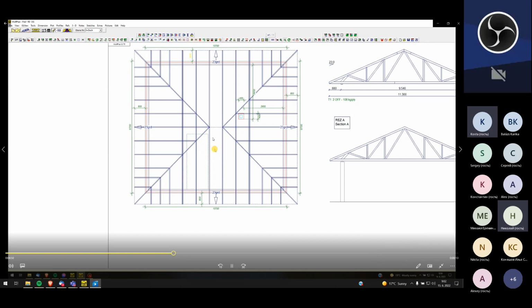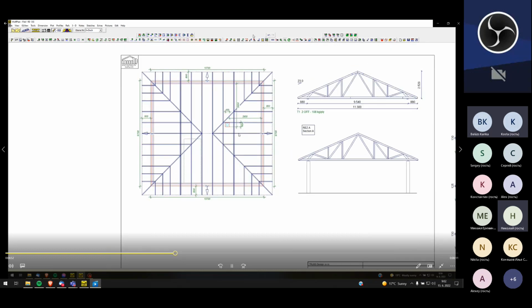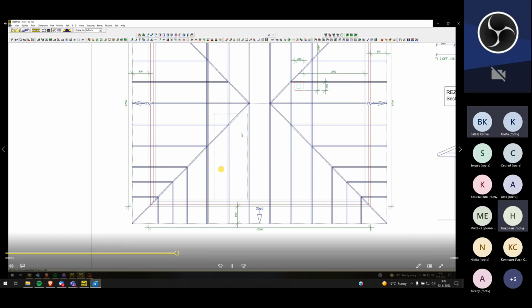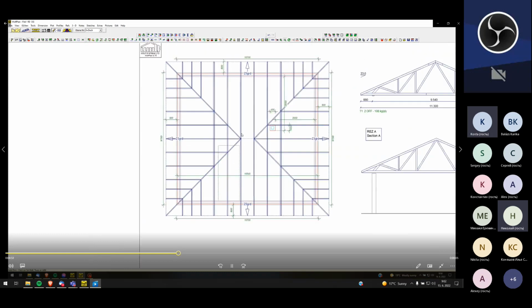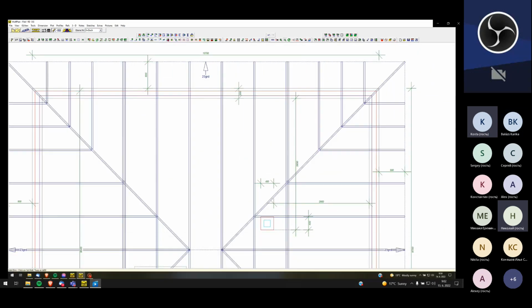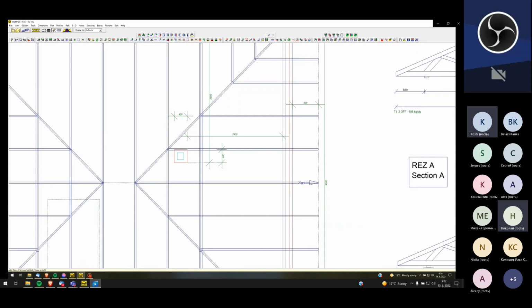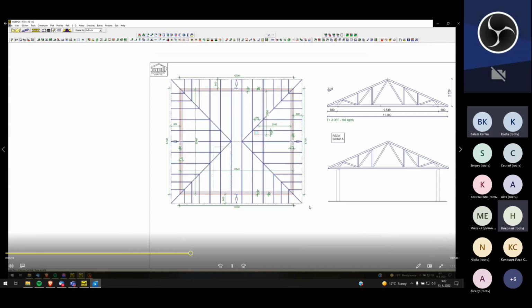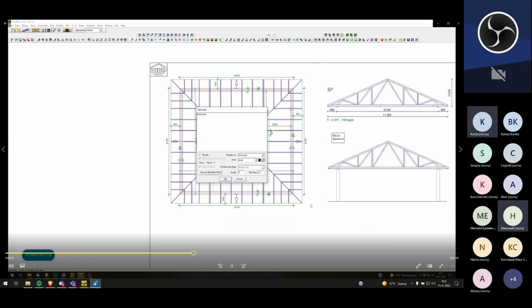But this full hip ending is solved with trusses and not with infill. The whole roof is solved with trusses without rafters. You will need the infill only in this place here later, sure. Separate timber elements will most likely be needed only at the corners.